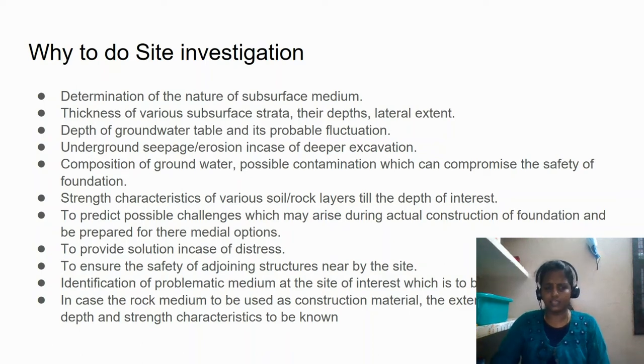So we have to see if any other problematic medium, cavities, may be present in your site. Nowadays sometimes we have a reclaimed site, we have wells. What the owner would have done, he has closed the well, and he would have put the site for sale. You won't know there was a well some 50 years before. Then once you start your construction, there could be a sudden subsidence of the ground, because in the well there could be made-up soil, it's not a natural soil. If the subsidence is going to be there, then your building will settle, your building will fail. So you have to identify if there are any problematic issues at the site.